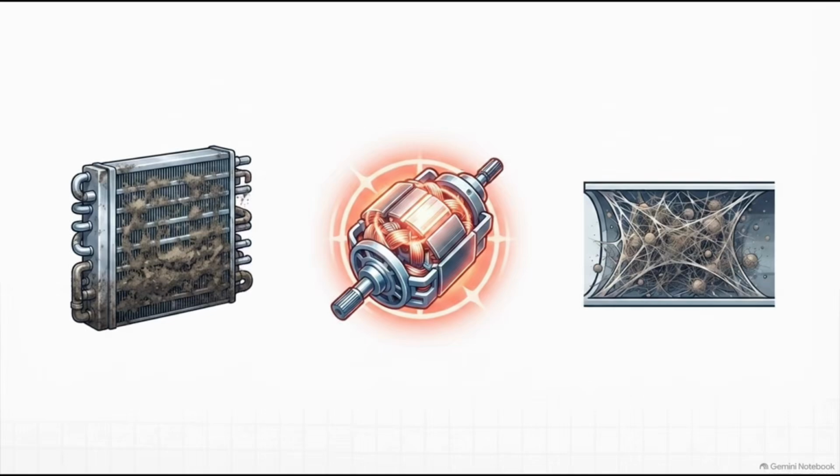That will drop your draft pressure, opening that furnace switch to prevent an unsafe burn. Then you've got blocked pressure tubing, loose or damaged wiring dropping the voltage, plugged pressure ports, you name it. Notice that way down at number 9 on this list is a legitimately failed switch. I mean, just look at how many other real-world system failures trigger that switch before we should ever even consider the switch itself as the culprit.